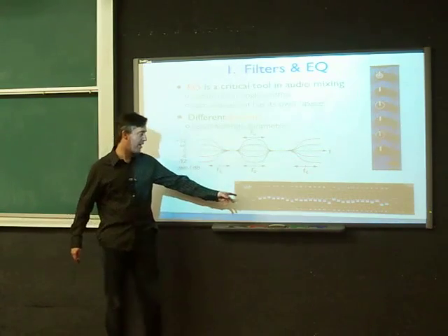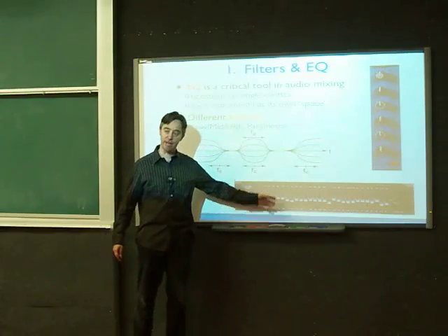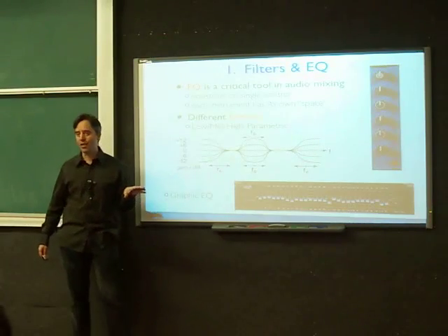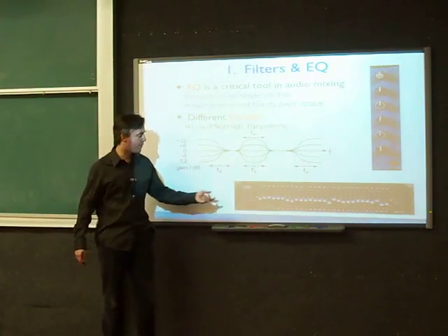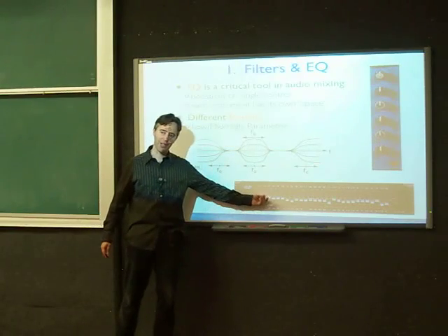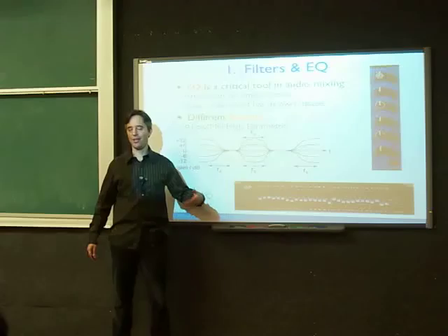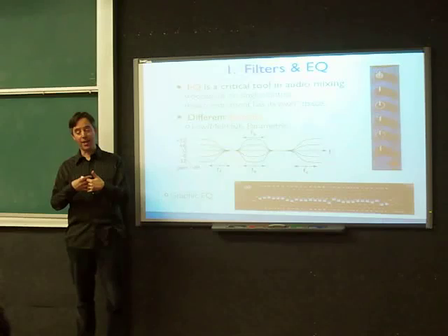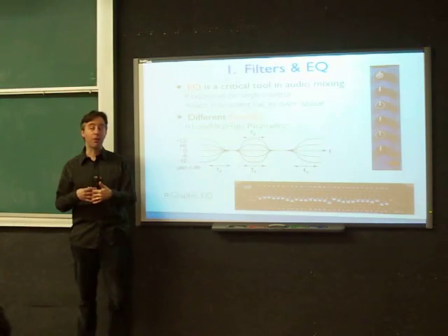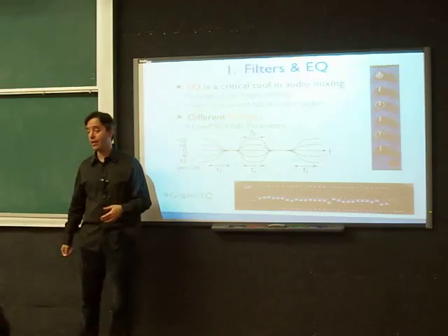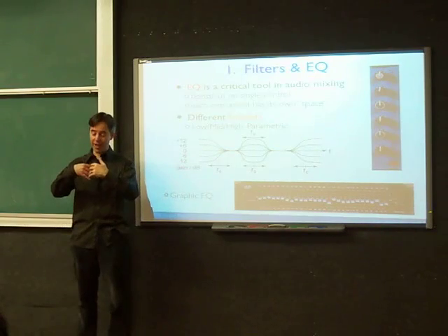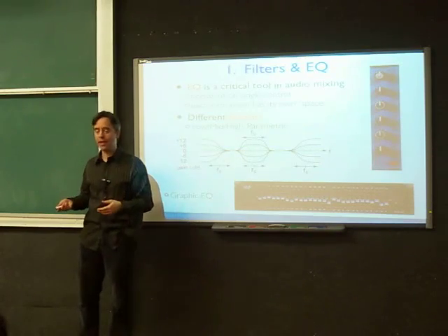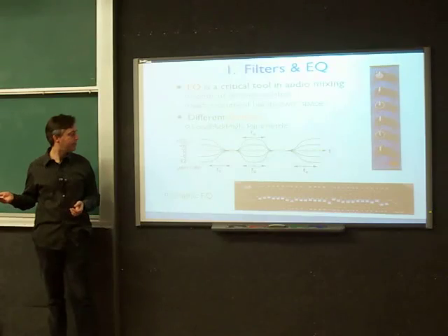All this is just a set of individual bandpass filters and then mixing the results. In principle, that's pretty straightforward. The only thing you have to worry about is what happens at the overlap between two adjacent bandpass filters, because then you're mixing two signals with overlapping frequencies, and you have to worry about the phase. If they're in phase, then they'll reinforce nicely. If they're out of phase, then you can get cancellation. You can get unexpected dips.